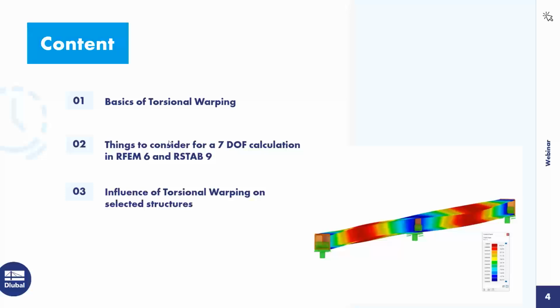I will focus mainly on simple and very clear examples to highlight the influence of specific parameters on the torsional load-bearing behavior that we can investigate in RFEM. For this introductory slide, I put a snapshot of a twisted I-section in the lower right corner. This is not by coincidence. In fact, most steel profiles are optimized for bending rather than transferring torsional load and are particularly affected by warping torsion. So we will mainly focus today on steel profiles and on steel sections. I will maybe lose some words also on solid sections, but this will not be the focus of this webinar.